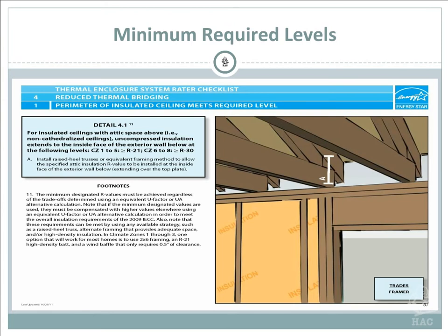So you're looking at this area right in here. You want to insulate. Remember, the insulation has to be a continuous insulation, or a continuous R value, from top plate to top plate in that attic. So as you see the houses that were built years ago, they would start sloping that roof at a 3/12 or a 4/12, whatever, and you got that pitch at the very end. When you insulated that attic at the very end, you were making contact with the outside roof and the bottom, and you were probably only putting in about 3 inches of insulation over that top plate, if any. So you probably had an R9 on the outside edge, and maybe you had an R38 in the middle, and it varies from there to the end.